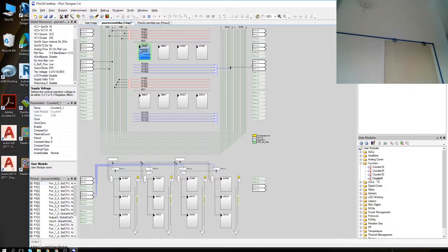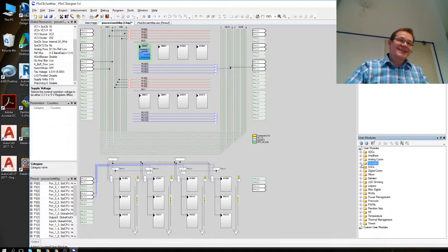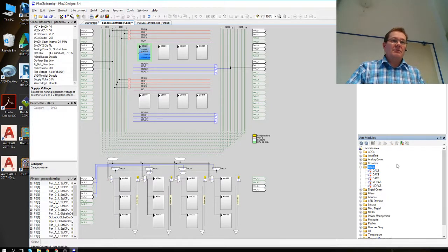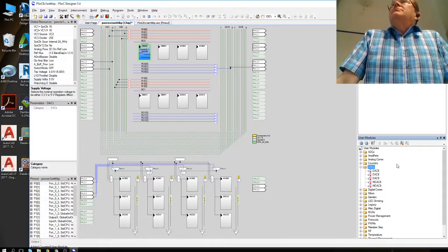You can actually start it from the top row and then connect it to the bottom row. They are routing kind of things. Those digital block inputs and outputs can be connected to almost any input or output of those digital blocks. So yeah, you can make a 64-bit counter. I don't know where you would use that, but you can do it. Oh, cascaded counter.